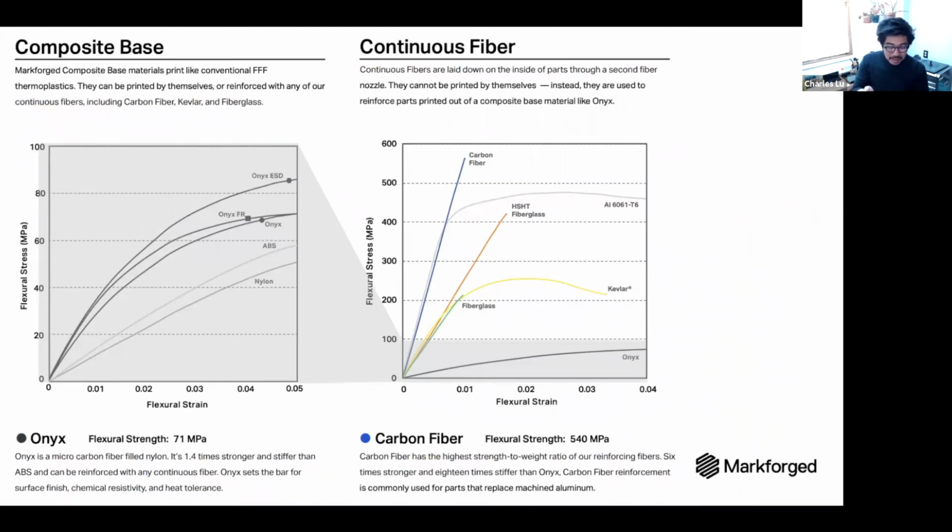It's because it is continuous. Also, you could see breakage at a very tight turn, but whenever we are doing those really tight turns, it tends to be because we're mimicking an isotropic pattern. So we're mimicking unidirectional per layer, stacking unidirectional layers on top of each other. So it will make a sharp turn at the end.